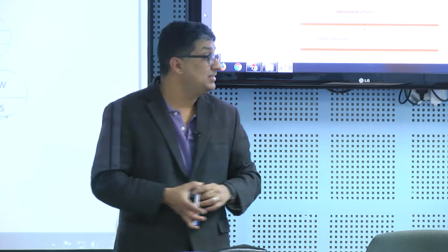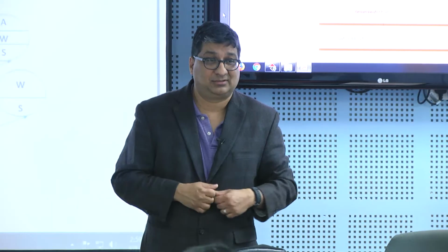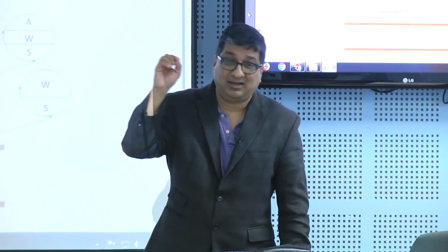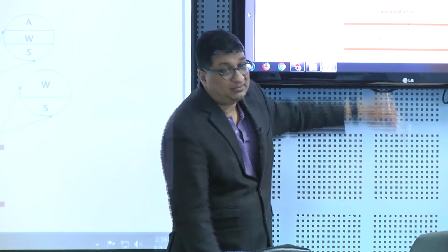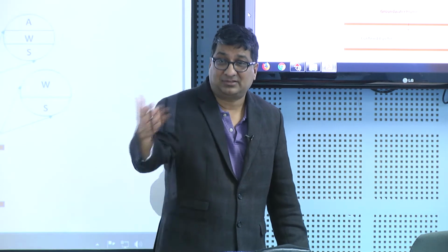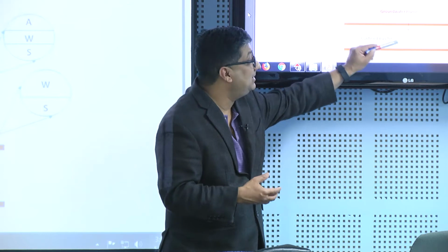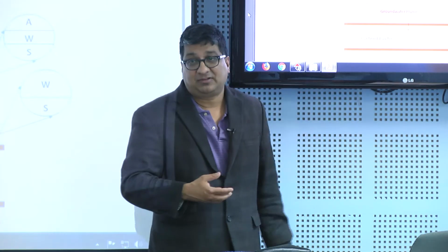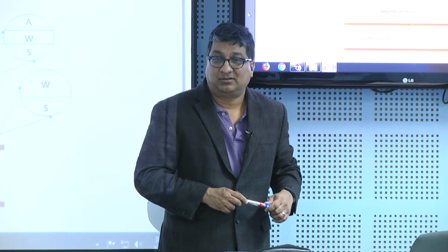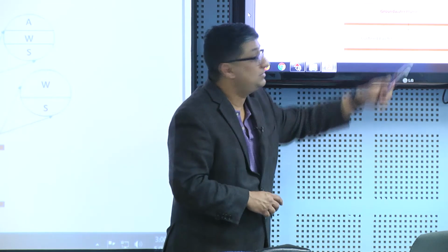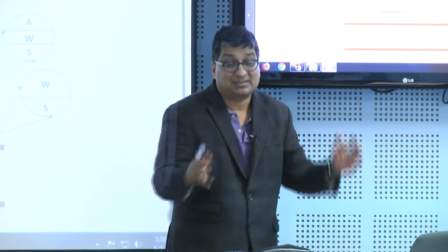Okay. So this confining layer, although we call it a confining layer, there is no material that's truly non-porous. So there will always be some small pathway that will cause some of this contamination to move into the confined aquifer. If it's very, very small, it gets diluted, so it's not a problem. But one of the big issues with this confining layer is, if you have some contaminant trapped in this layer, it will sit there for years and years and years, and you really cannot put a well to pull it out. And it's too deep for us to excavate and pull it out. And so it gets contaminated, and it stays contaminated for a very long period of time.